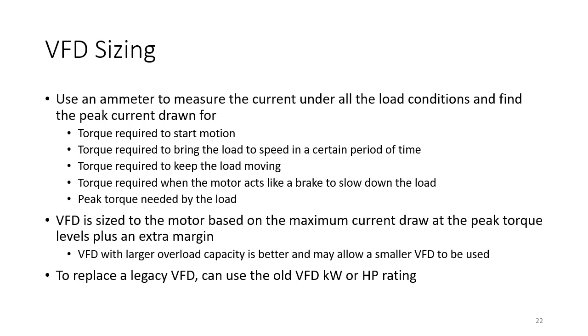It's generally possible to size a VFD quite accurately to the motor size. You could also look at the VFD and compare it against the motor, and you may say I can actually use a smaller VFD because maybe my peak torque isn't as high as I'm expecting, so that would allow you to reduce the size of your VFD. But you need to be a bit careful there, because if ever things change in the future, then you might need to replace your VFD.